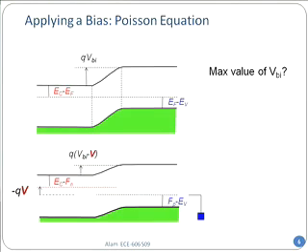You see, I have not drawn the red dotted line and the blue dotted line all the way to the other side. You may notice that. The rule, which I'm going to explain later, is that you have to stop. The red line must start from the N side and continue all the way to the other side of the junction and then stop. Similarly, for the blue one, you start from the P side, whatever is the dominant side defining the Fermi level, you continue all the way to the other side of the junction, and then you stop. Beyond that point, you don't continue.